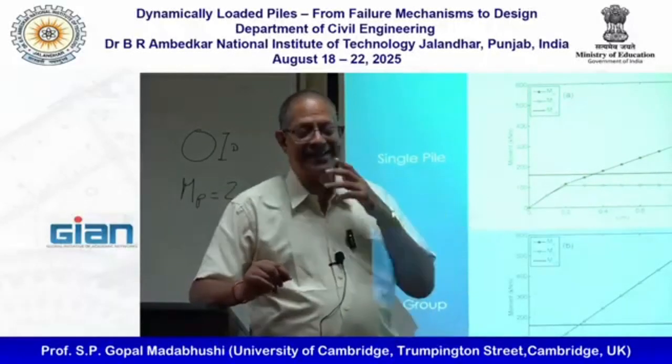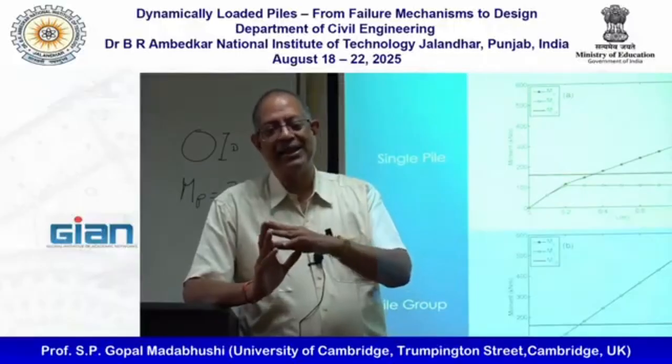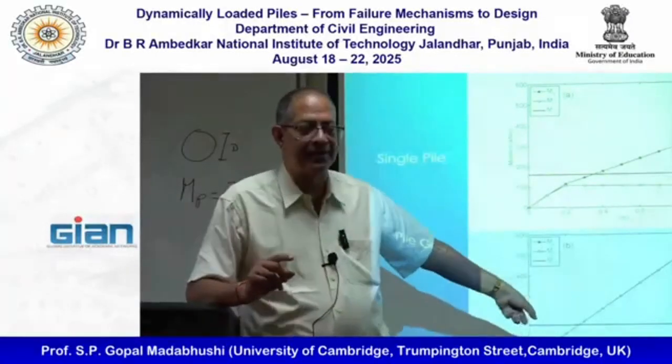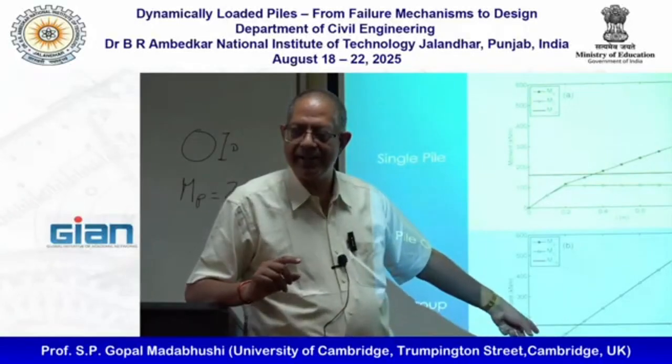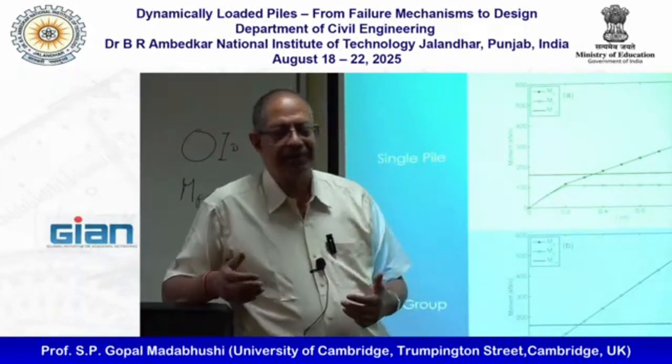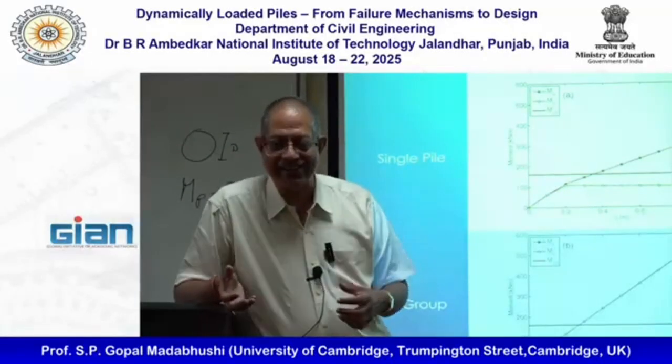The problem with piles is, once you reach the plastic hinge, that means I've already undergone 0.3 meters for this particular case, right? Then the P-delta effects start to dominate, because I still have to carry the axial load.